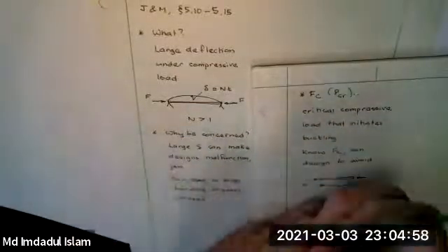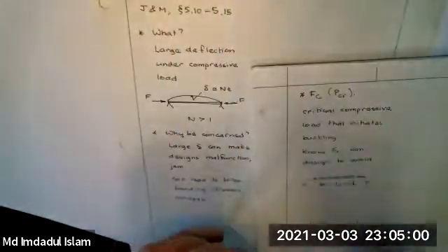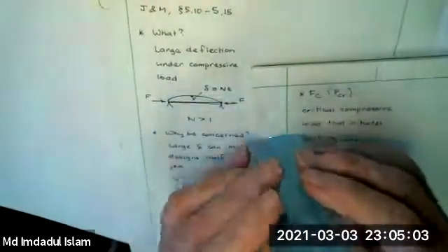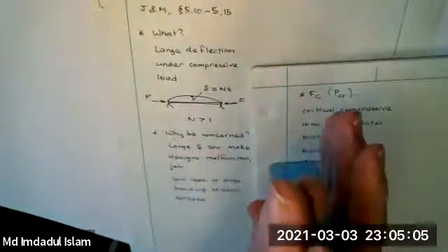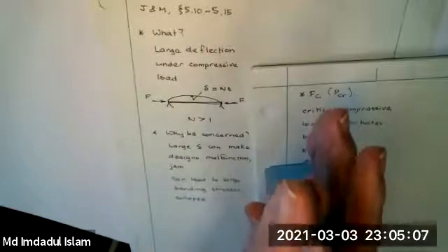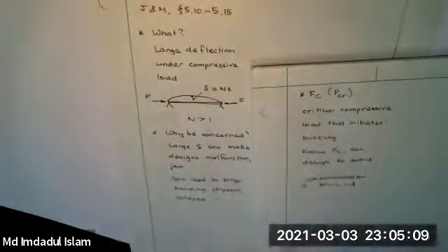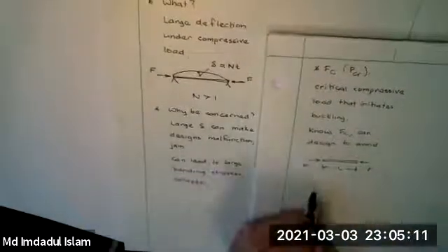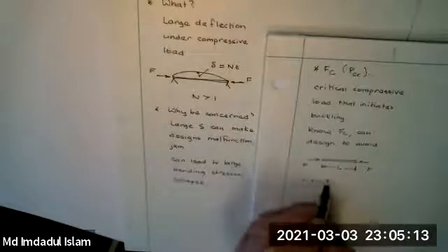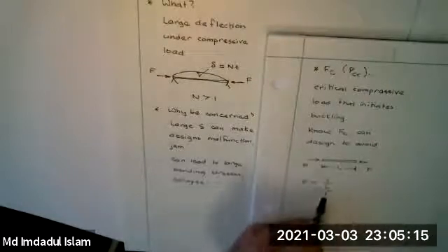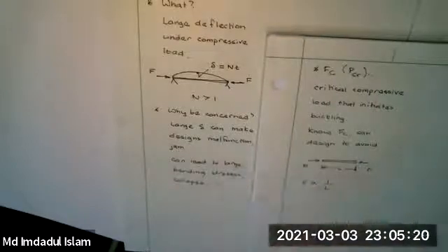If I was to turn it crossways like this, I can push very, very hard, and I will not buckle it. So you would expect then that F is proportional to 1 upon L. If you make things bigger, length longer, then they're going to get easier to buckle.